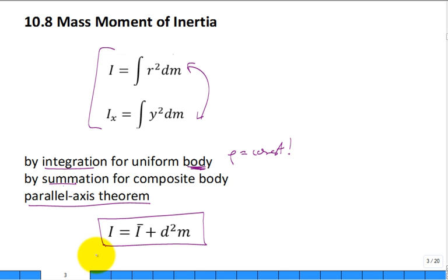Change the m to an a. That's it. It's really pretty easy, isn't it? So if that was an a, then you'd say, oh, there's the parallel axis theorem for area moment of inertia. And then here you have it for the mass moment of inertia.